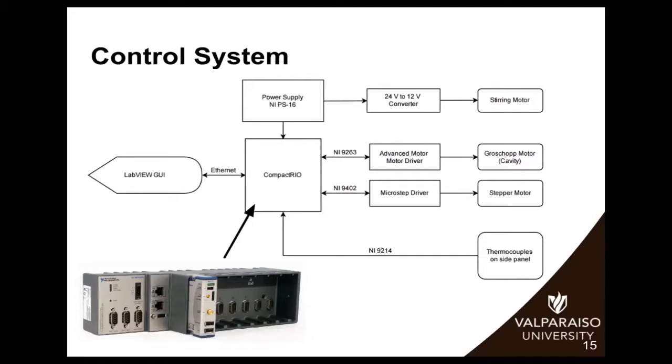And then another part is that the steering motor up here is being controlled directly through the power supply through a 24 volt to 12 volt converter. And so that part is always running, but the rest of it is controlled through the compact radio.